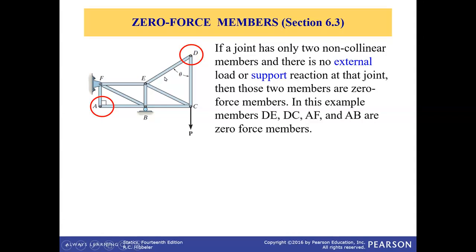Now the question is, why do we even have them if they are zero force members? So the answer is they are zero force members only for the given loading condition. For future reference, if the loading changes and the load is applied at D, then they are no longer zero force members. So zero force members are not useless. Only for the given condition, they don't play any role. But when the loading changes, they may play a role. They are actually important and they play the role in carrying those loads.